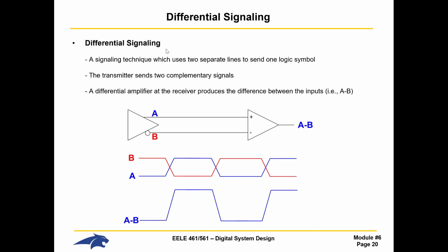And up until now, we've looked at coupled lines as basically kind of a nuisance, right? I mean, you have a 1 or a 0 you're trying to transmit to a receiver, and some other trace gets too close to you, and all of a sudden it alters your impedance. And so the trace that got next to you was a victim in the sense that you coupled some of your energy onto it, but it was also a nuisance because it changed the impedance of your own line. So it actually caused reflections on you just because it came too close.